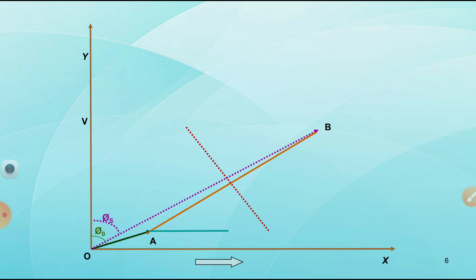Okay, this indicates the constant losses, or we can say the fixed losses. What are the fixed losses here? That is the mechanical losses and iron losses. Automatically, copper losses change based on the load current. The vertical distance from A to the X reference axis indicates the constant losses.